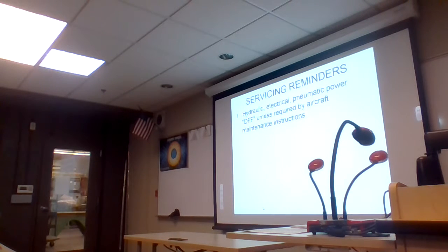Hydraulic, electrical, and pneumatic power off unless it's required by the aircraft. Common sense: if you don't need to have the electricity on, you don't. In some cases you have to, but again, the service manual will tell you if you have to have electrical power applied or pneumatic power on or off, whatever the case may be. Use the service manual to see what procedures are required.